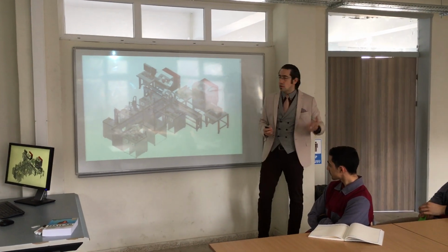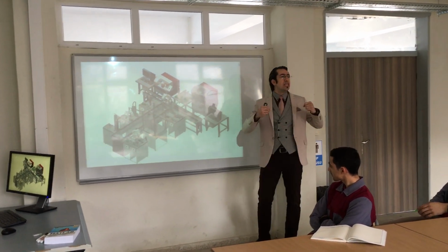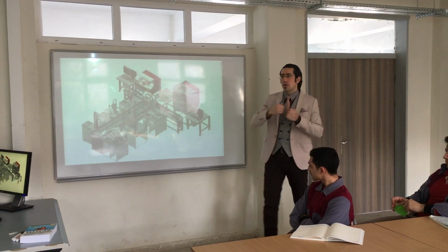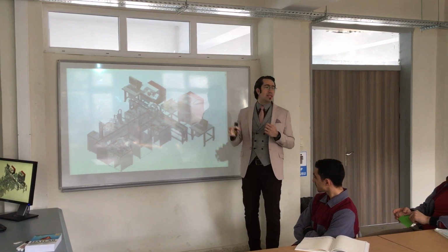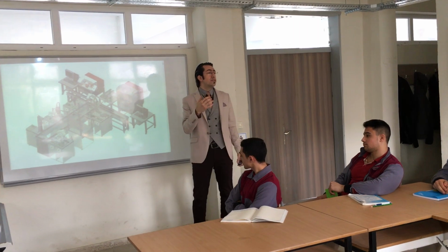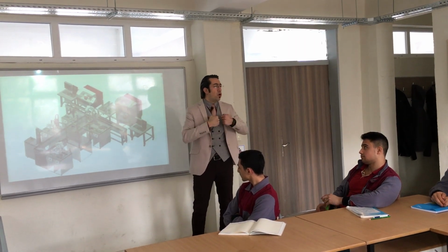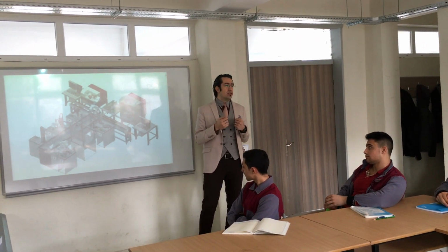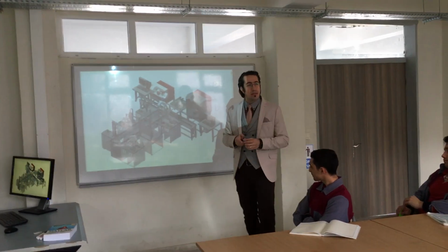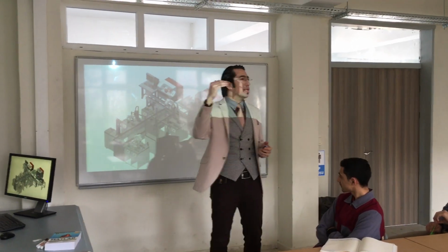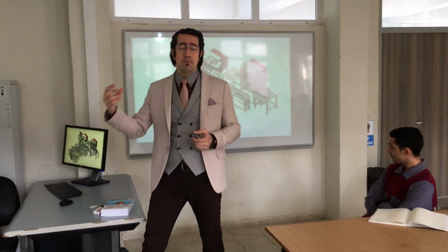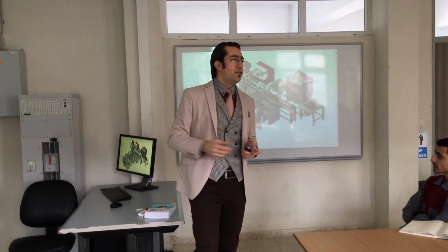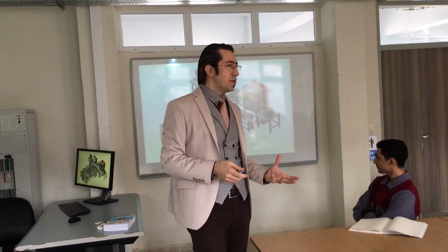In industry we use a hydraulic vice, but in this education system we use just a pneumatic one. If you need more power, force and pressure, you can use hydraulics, but we don't need a high level of pressure because we use small and soft materials here, for example polyamide, aluminium, etc.